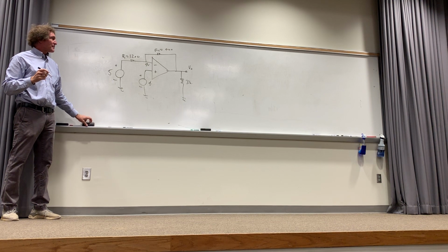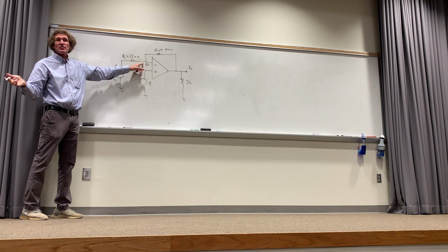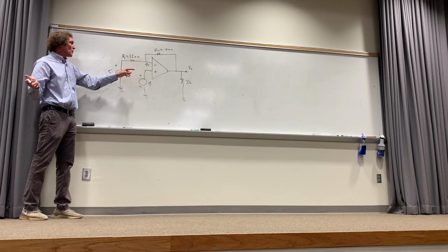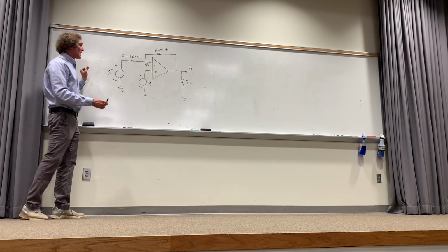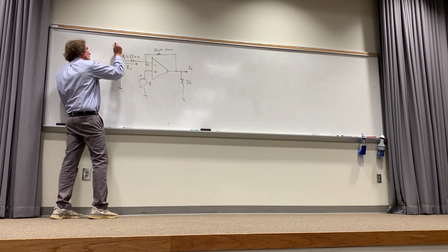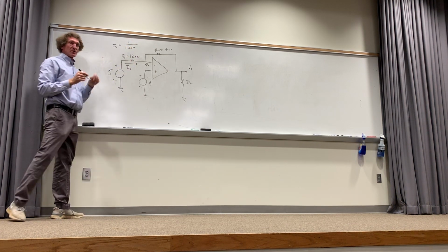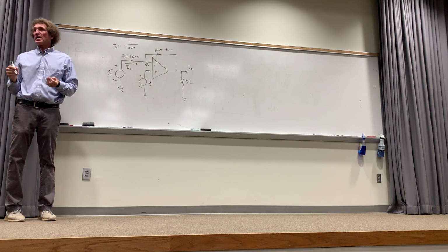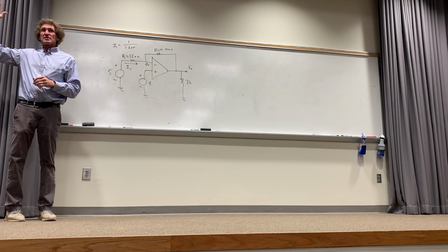Now, with that, if that's 4 volts here, do you all agree it's 4, right? Has to, because if you've got the voltage on one end, you've got the voltage on the other. It's that simple on the input. If that's 4 volts and this is 5, there's 1 volt difference across there, right? 1 volt divided by 1200 ohms means this current, and I'll call it I1, is just equal to 1 over 1200 amps. Agree, class? Voltage divided by resistance is current. How many see this? You might be bored to tears because you see it so easily, but I gotta make sure you all see it.